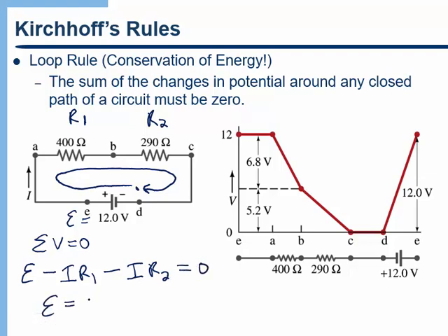Well, notice that the way I've been saying it is the voltage of the battery is equal to the sum of the voltages across the resistors. Well, really, that just comes from Kirchhoff's loop rule. Okay, so it's really not, again, something that we haven't talked about. The loop rule is really just a statement of conservation of energy.